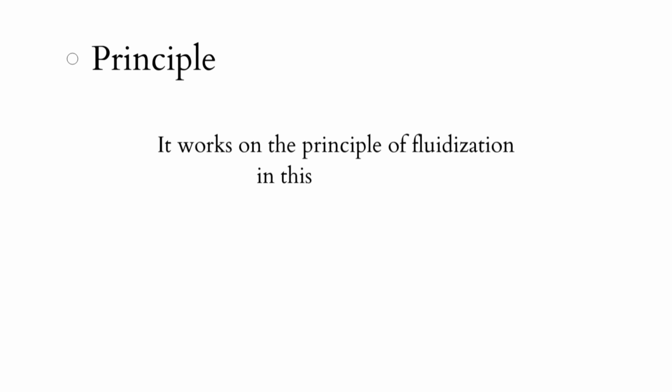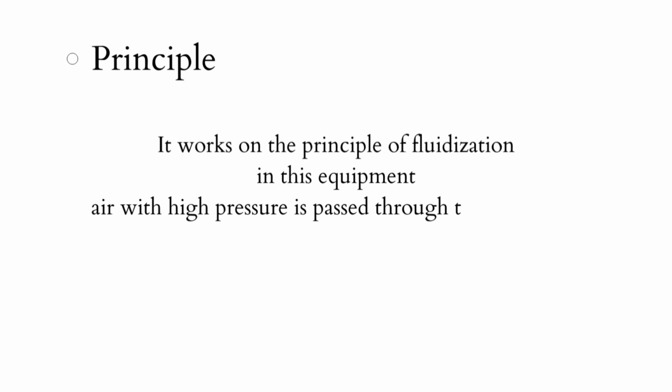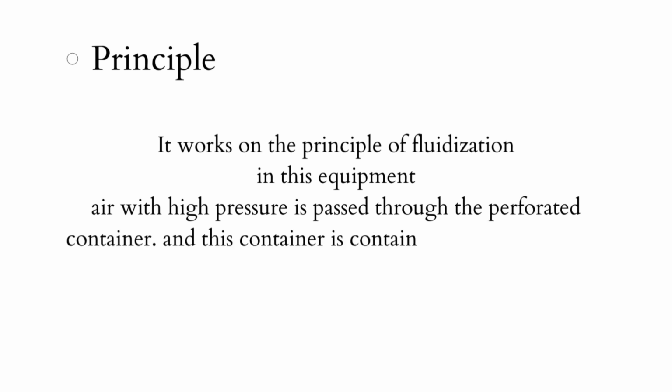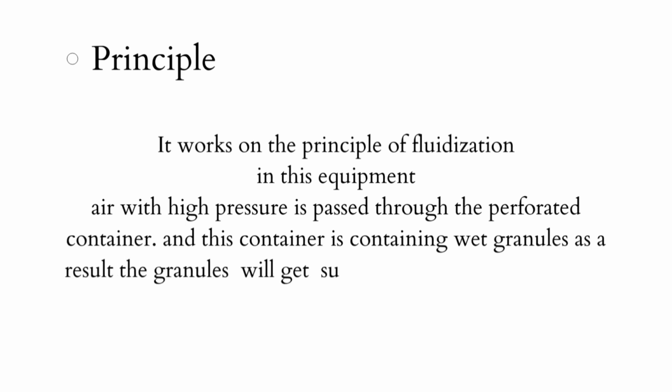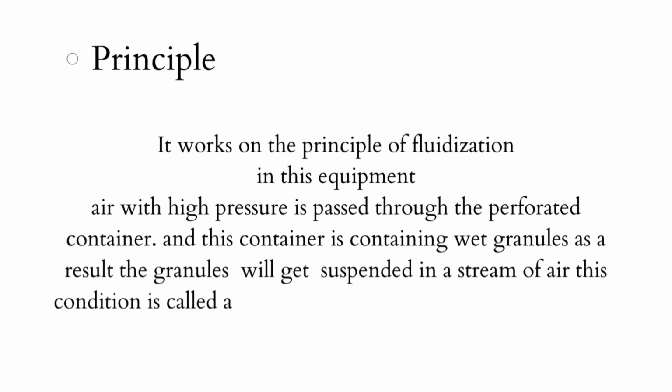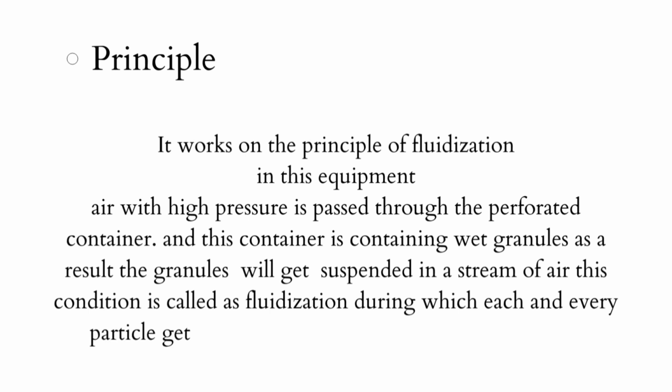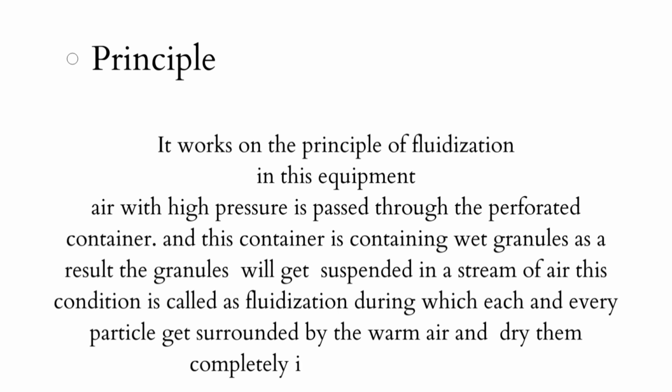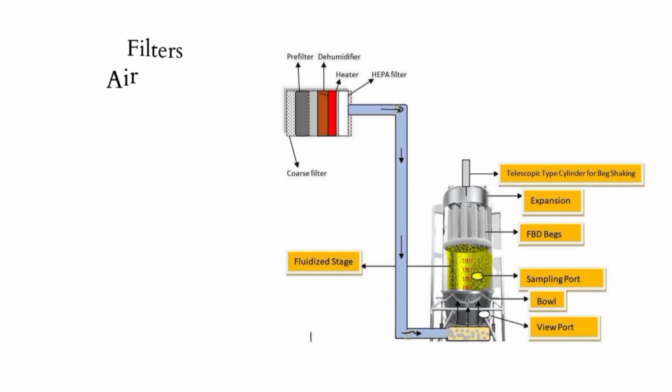Okay, let us start with the principle. It works on the principle of fluidization. In this equipment, air with high pressure is passed through a perforated container, and this container contains wet granules. As a result, the granules get suspended in a stream of air. This condition is called fluidization, during which each and every particle gets surrounded by the warm air and is dried completely in a fluidization state.